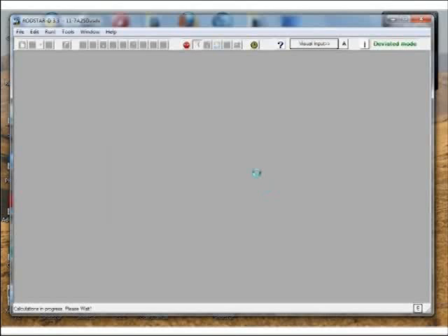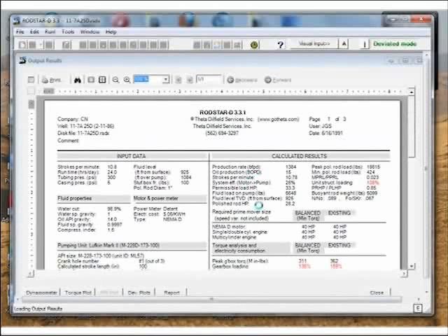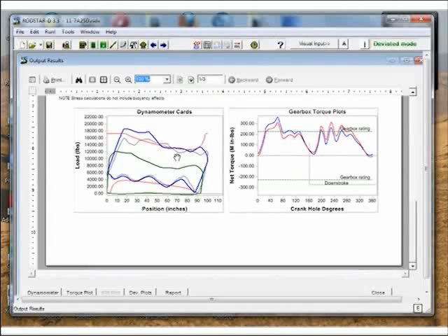That number, of course, depends on how accurate your production data is. If your production data is not accurate, the pump efficiency calculated by xdiag will not be accurate. And to get a good match between the predicted and the actual cards, you need to have the right pump efficiency. That has to do with the integrity of the pump. Okay, so let's take a look here. Well, we're not quite getting the match. It's not bad, but here especially there is a difference.